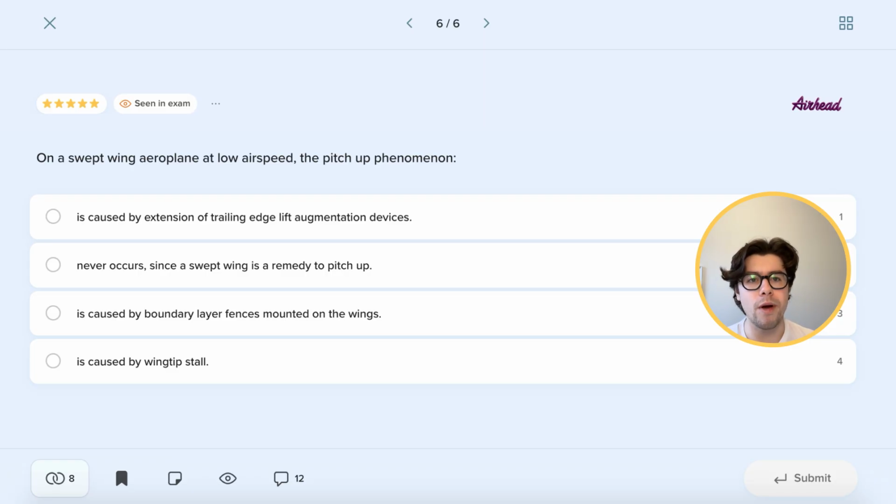So remember that the swept wing is prone to deep stall, and this is actually quite a big threat when it comes to flying swept wing, especially after flying square wings in GA. In case of a swept wing, because the wing is further to the back and the downwash is different across the entire wing, the tips of the wing will actually stall first. This is also why there is some twist added to the wings, in order to change these characteristics.